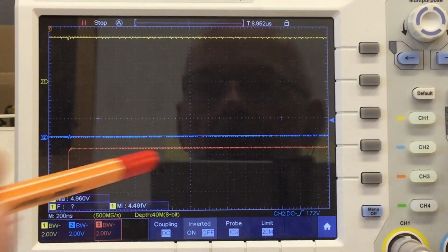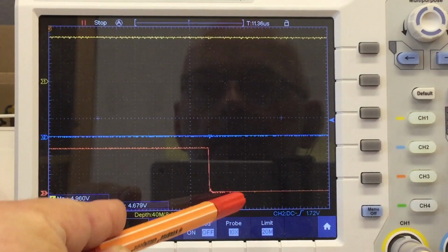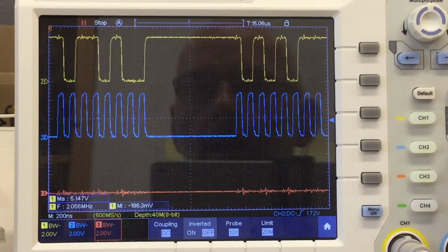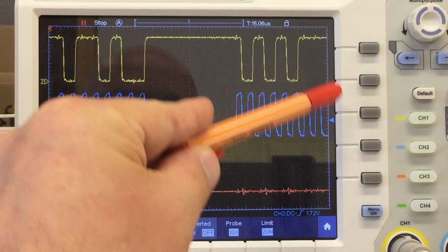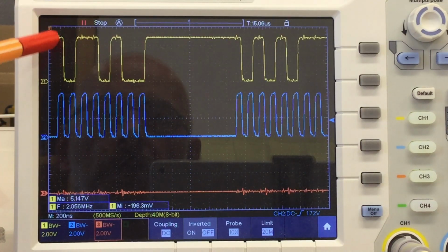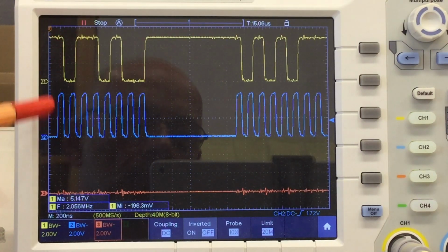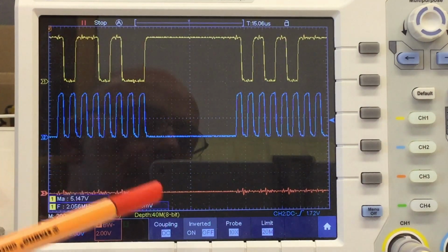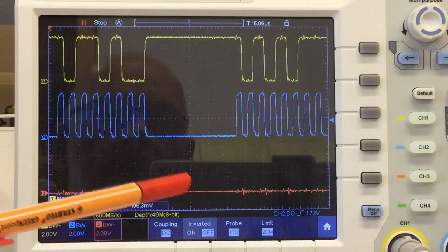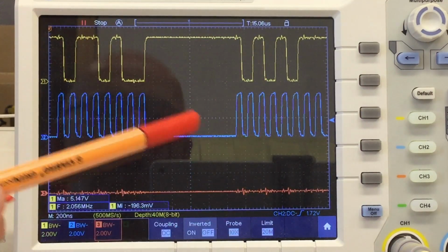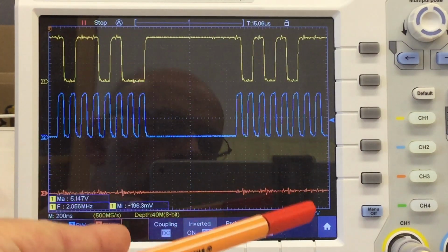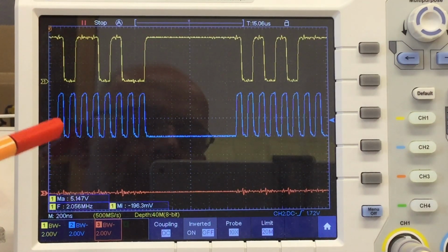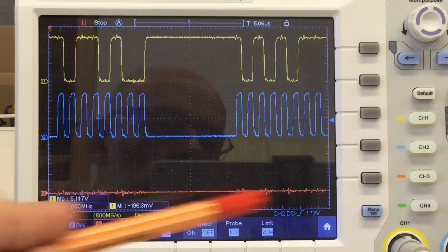You see chip select is going high again, chip select is going low again, and here we go. And you see for that next 16-bit data package, the first bit is high. And you remember the first bit was the channel selection. And I'm driving here a dual channel DAC, and the library is writing, alternatingly, the value for channel 1 and channel 2. So the first bit is alternating between high and low in each data package.